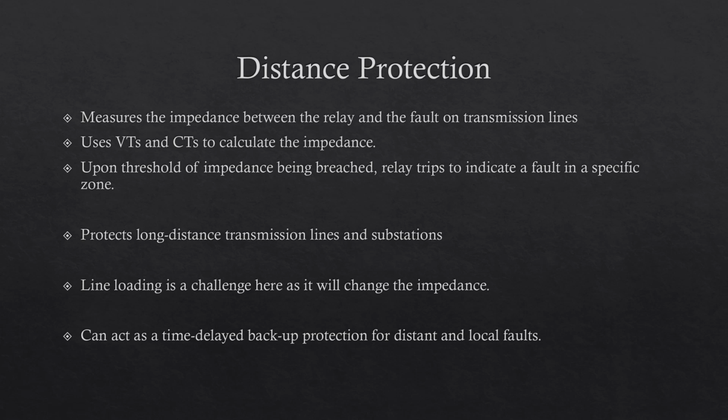So let's say we want to protect a transformer or a feeder. We then have earth fault, where we detect ground faults very fast. It monitors the three phases or the phase to earth, line to earth. Used for transformers and generators again.